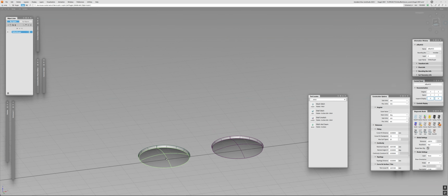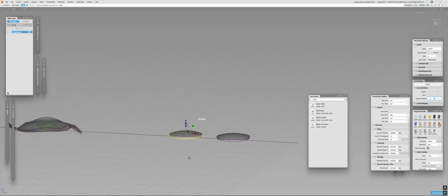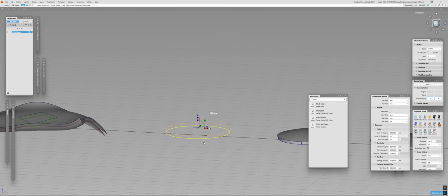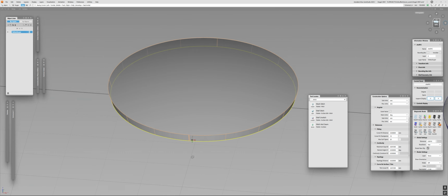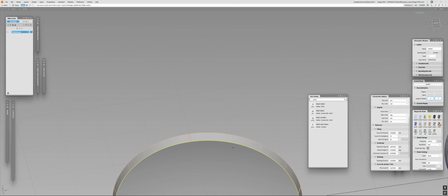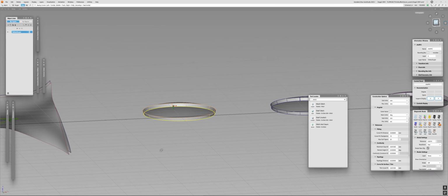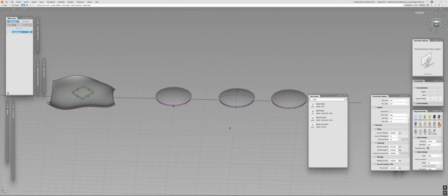For example, let me just delete this stuff from here, and I will stitch it again. Okay, now as you can see, this bright yellow line means that this BREP or stitched model is stitched only here, and you have an empty side here, so it doesn't have any internal volume. This means that this is a closed BREP, and this is an open BREP.